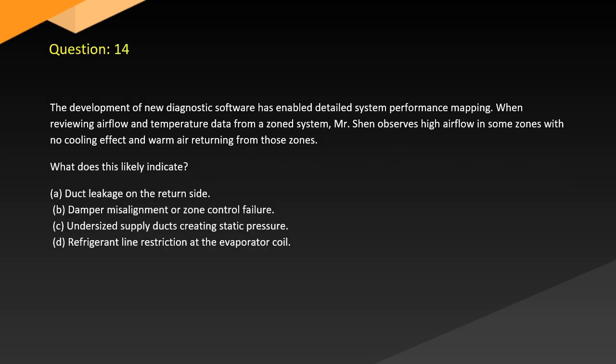Question 14. The development of new diagnostic software has enabled detailed system performance mapping. When reviewing airflow and temperature data from a zone system, Mr. Shen observes high airflow in some zones with no cooling effect and warm air returning from those zones. What does this likely indicate?